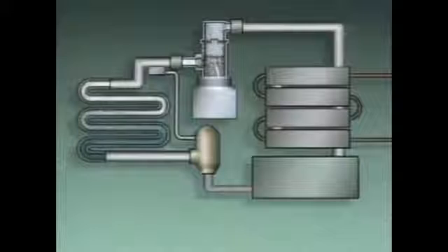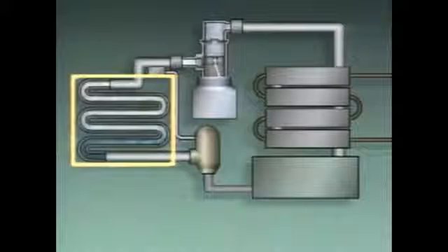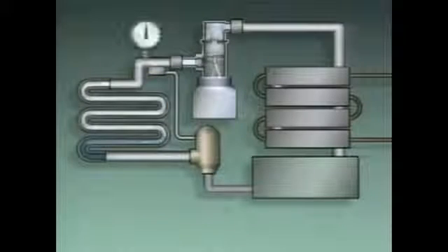In a system with a reciprocating compressor, reduced refrigerant flow causes the pressure in the evaporator to decrease, and the control system may shut down the compressor. When the compressor stops, the refrigerant begins to warm up and the pressure starts to rise, so the compressor quickly restarts. Then the pressure is reduced again and the compressor again shuts off.